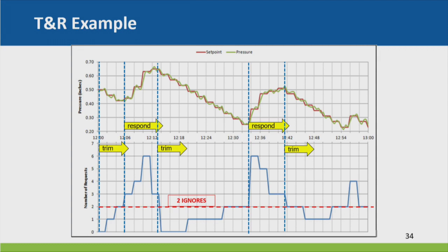We did another research project to try to see if we could do some feed-forward kind of stuff to make it so that it just didn't go up and down so much. Because a lot of building engineers don't like that. And you certainly want to make the time cycle on this thing long. Like here, it peaks at 12:12, and here at 1:42, it peaks again. So that's a pretty broad range. You want to make sure that it isn't going up and down really quickly, or the building engineer will turn it off in seconds, as well he should if it's bouncing around. So you make it sort of broad to make that go away.